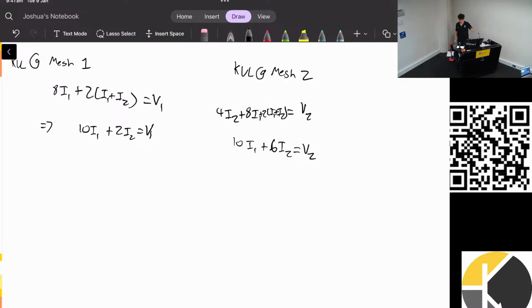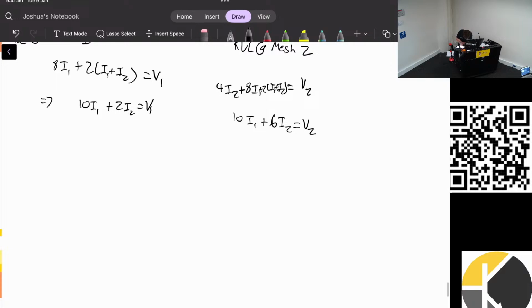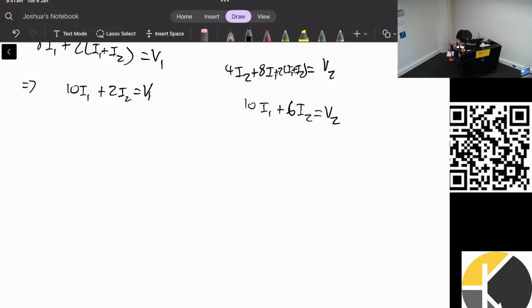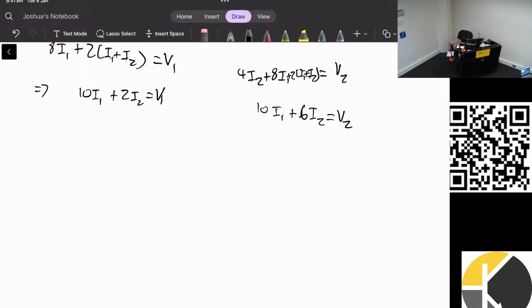There's two ways of solving this. I'm going to show you the first way, and then I'll comment on the second way. The second way, which is really easy, is to write the z parameters and take the inverse of the matrix. That's how you convert between z and y. The easy way to remember it is that normal admittances and impedances are inverses of each other, 1 over. You'll see that quite a bit, where you get nice parallels between them. But I'll show you the other way, which is that I am going to solve these.